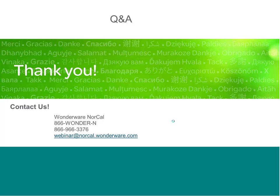Okay. We have an outdated and no longer supported SCADA system different than Wonderware. Can Wonderware import and store my historical data? Okay, that's a good question. The answer is, what kind of format can we get that data out in from your existing SCADA system or your existing historian? If you can get that data out into a CSV file or Excel file, then we can import that data into the Wonderware historian.